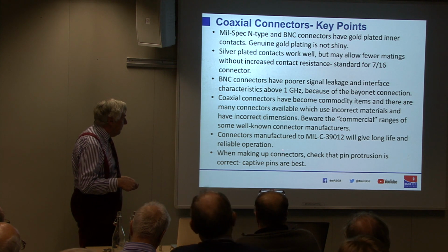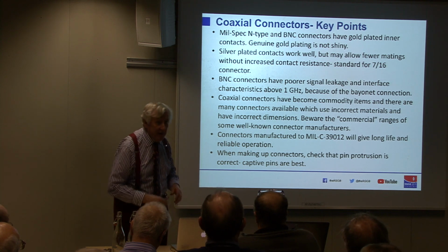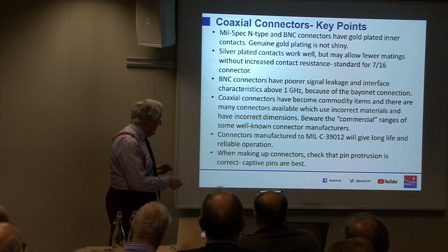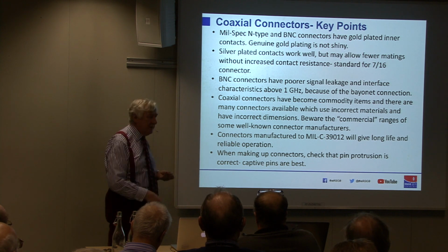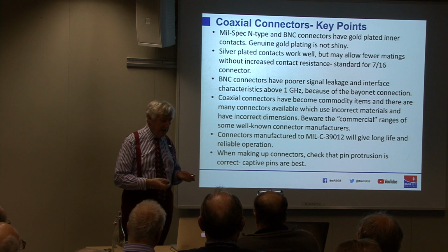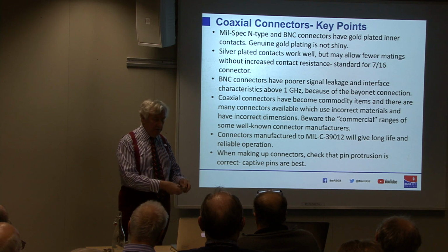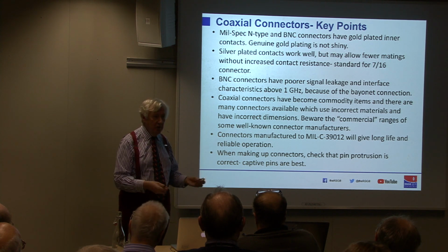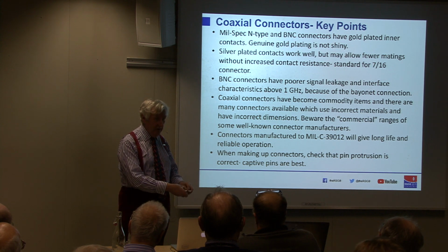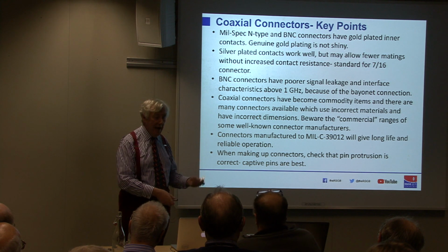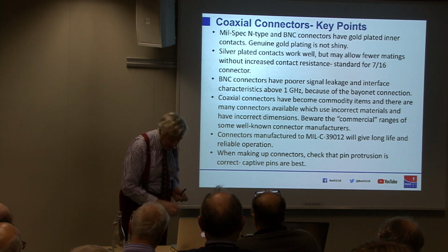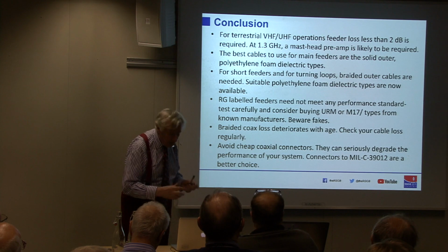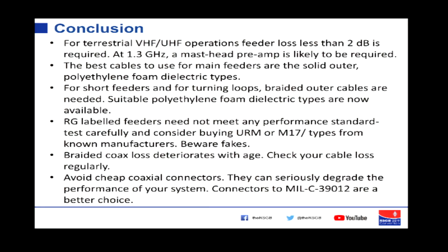And finally, when making up connectors, check that the pin is in the right place. Captive pin connectors are best, but for any connector you've made up, just use your thumb. If you take your thumb across the connector, you should just catch the pin on the back of your thumbnail. If you don't, it's in the wrong place. If it's sticking out a lot, it's wrong. If your nail can just go over it, it's too far back, and it will do what some of John's connectors have demonstrated.